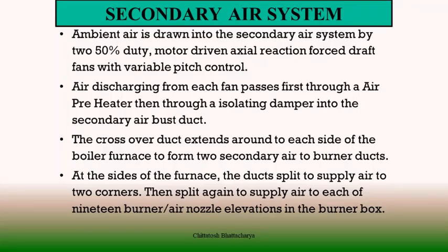In general, there are two types of systems. One is a cold PA system and the other is a hot PA system. In case of cold PA system, PA fan is drawing cold air from the atmosphere, and after passing through the air preheater, part of the primary air is getting heated and some part bypasses the air preheater, and that is mixed with the hot primary air, and then that is going to the milling system. So naturally this is the cold PA system where PA fan is drawing cold air from the atmosphere. But in many smaller units where PA fan is not drawing the cold air, it is a hot PA system, and in hot PA system FD fan is supplying the primary air as part of the total air.